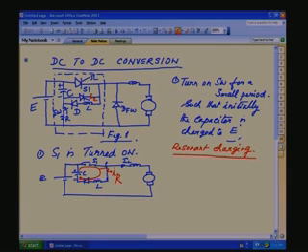So, how will the waveform be? The resonant charging of the capacitor, the whole voltage and current waveform will look like this. The capacitor initially charged to E here, due to resonant charging, it will go like this and come to minus E here. So, part of a sinusoidal, that is, it will charge in the opposite direction.